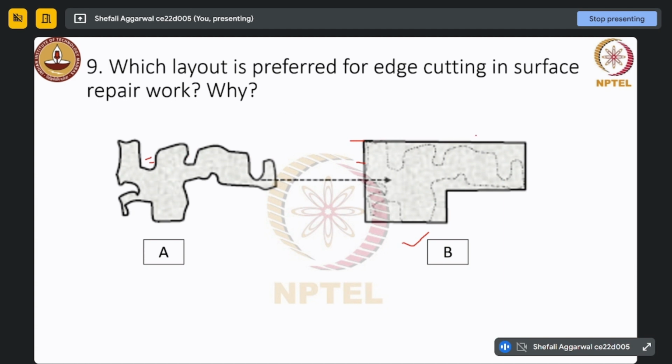But when we are using a definite perimeter, even if shrinkage is happening, this complete surface will provide a good bond to the base. In this case, all the surfaces are disoriented. There is no connectivity between the different surfaces. Whereas if we provide a definite border, our connectivity with the base structure is more, and it is a stronger bond between those two materials.